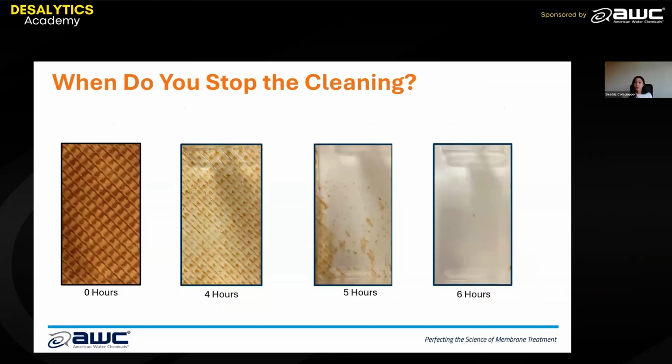But let's talk about also the protocol. Time is a big factor when it comes to cleaning. So how do you know when to stop cleaning? The right answer here is when the foulant is completely removed. But that can be a little bit hard to know, especially when it's the first few cleanings. Usually I recommend that you do a cleaning study before you try to clean a new system. It's the best way to understand what chemical to use, how long you should use it. The protocol is just as important as the chemical selection.